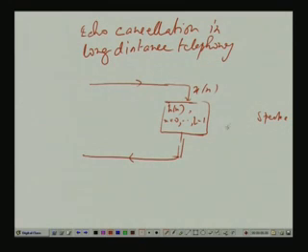What comes out here is echo plus this person's speech. If this person is speaking, what comes out here is x n convolved with this sequence, that is the echo, plus this person's speech.